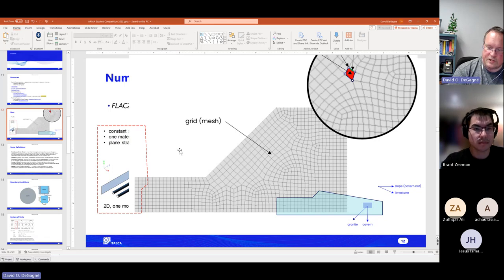We generally don't do all TET modeling except in 3DEC. And again, it's all automatic. As you'll find, if we introduce things like circular tunnels or horseshoe sort of curved elements into the model, you're probably more likely to get more tetrahedral type shapes.